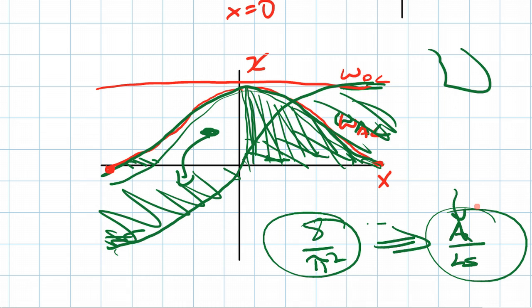And we could easily understand the spring constant and the relationship. You could derive it by thinking, okay, if I make this bar bigger, if I make the area bigger, then I will have to apply more force to get it to move the same distance. Let's just draw the little bar. If I increase this area, it'll be more stiff, like pulling a really stiff bar, compared to pulling on a thin wire, or a really long fat pole. The fat pole is just going to be a lot stiffer. And that's why the A is on the top. As you increase the area, you increase the stiffness.